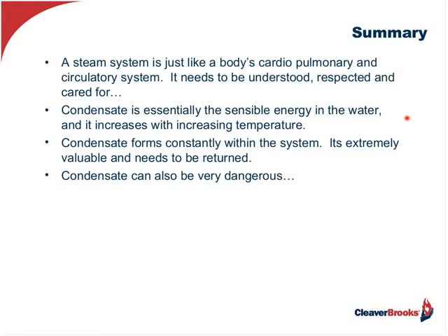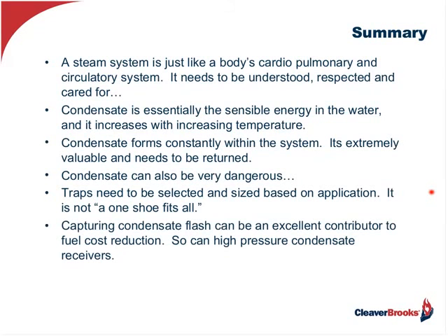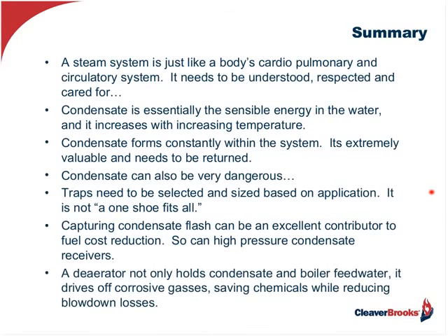Condensate can also be very dangerous. Traps need to be selected in size based on application. It's not a one-shoe-fits-all. And capturing condensate flash can be an excellent contributor to fuel cost reduction, and so can high-pressure condensate receivers. Finally, a deaerator not only holds condensate in boiler feed water, it drives off corrosive gases, saving chemicals while reducing blowdown losses.